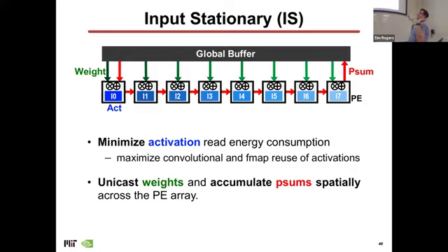But now you have this large network that's sending the weights to each individual element, and then each element is storing the input activations associated with the particular layer that you're flowing through. And again, this is not super popular because these change all the time, and it's usually easier to program the weights so that you flow through the new data instead of reprogramming the array for basically every different input, right? This necessitates reprogramming on every input.